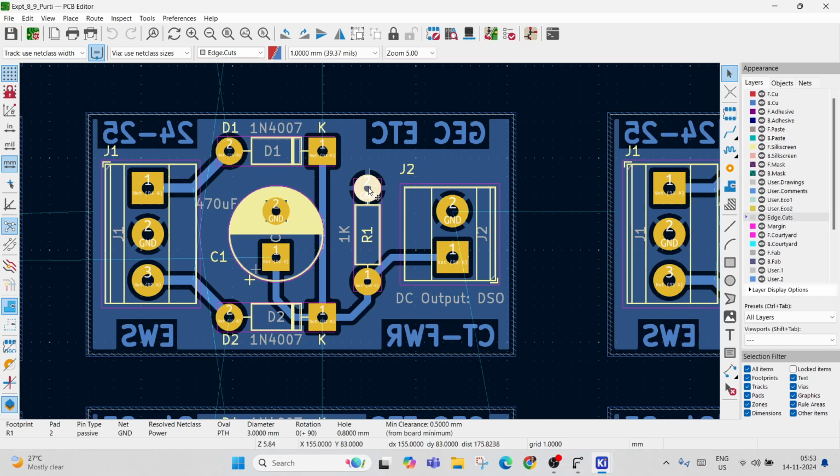So that means I'm going to be making holes of 1.415 mm, and the resistor terminal has 0.8 mm diameter. The pin itself has 0.8, which means there is going to be a gap of 1.415 minus 0.8, which is 0.515 mm gap, which has to be filled by solder.